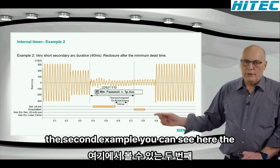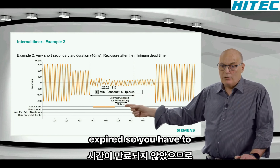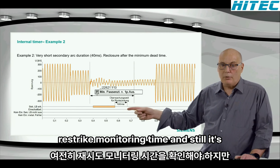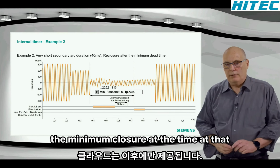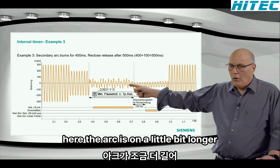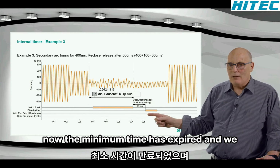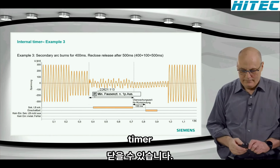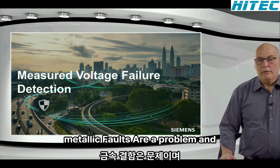The second example, you can see here, the arc was on a little bit longer, but still the minimum closure time has not expired. So when the secondary arc extinguished, you still have to check the restrike monitoring time, and still it's too short. The closure is only given after the minimum closure dead time. At that example, here the arc is on a little bit longer. So you can see the secondary arc extinguishes, the restrike time. Now the minimum time has expired, and we can close immediately after the restrike timer. Metallic faults are a problem and blocked.